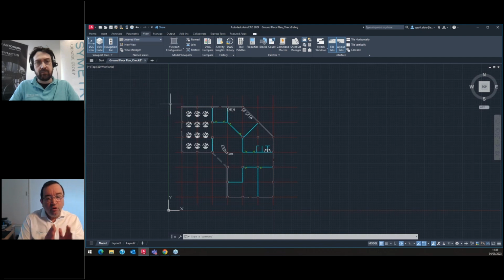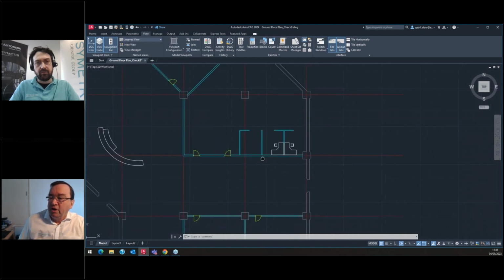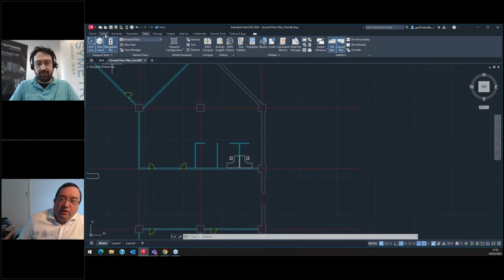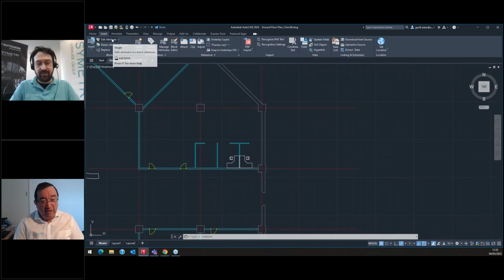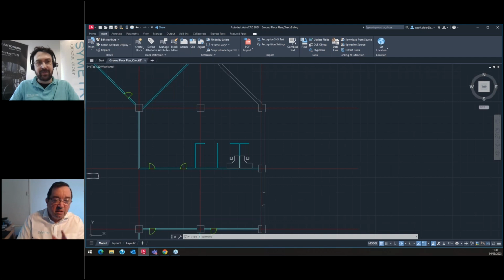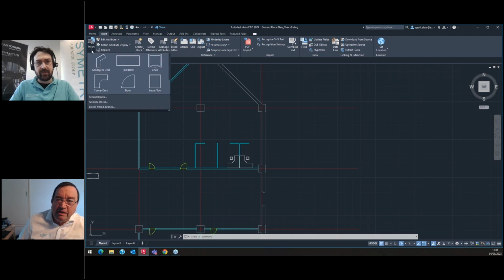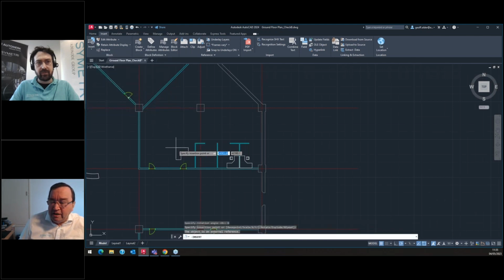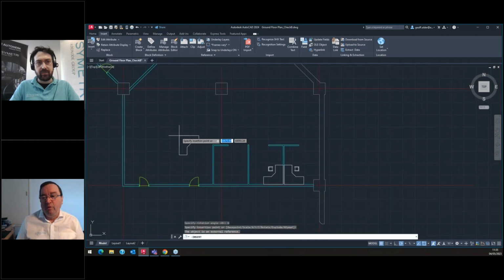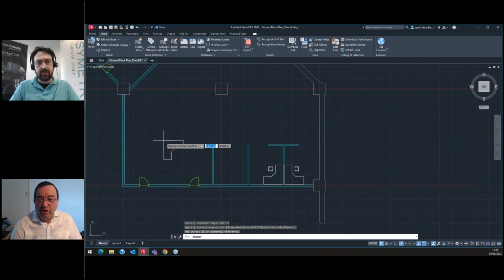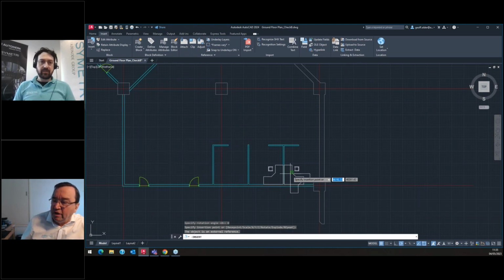Now, those are two features I quite like in AutoCAD, in our way forward. If I move over, there's a couple of bits here that I sometimes find quite useful. This is in my 2024. I must admit, sometimes it does flicker a little bit, but let's see. If I click on an insert here, for example, and I'm placing a block, let's say my corner desk here, you can see the arrangement of the block in association with the cursor there. And you can see that I've got a desk in the corner here.